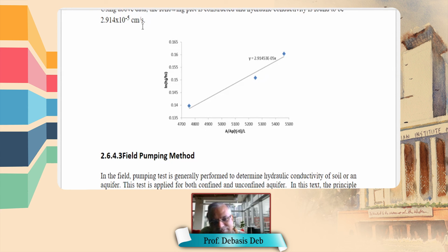So if the water is here beneath your house, next day it will move maybe 5 centimeter only. Okay, there are also rock layers like this. It is just not moving. And then if the water is not moving, what do you do? You have to increase the hydraulic conductivity. There is no other way, because pressure difference you cannot change.